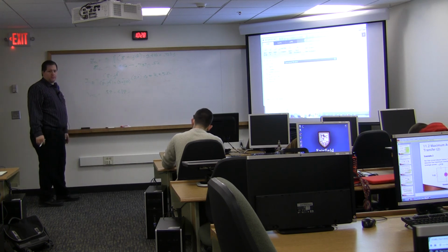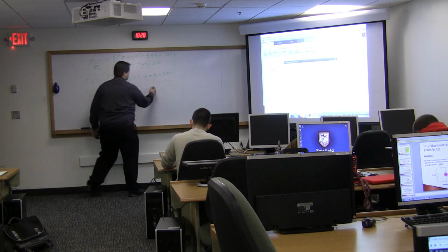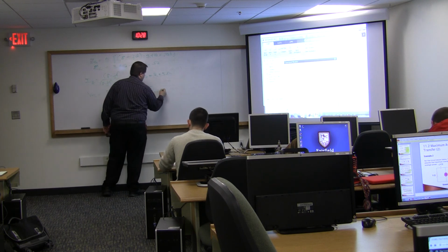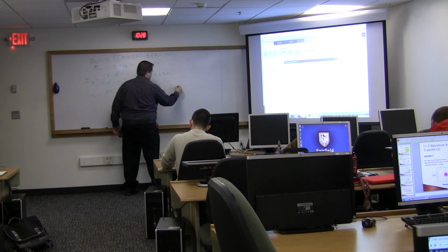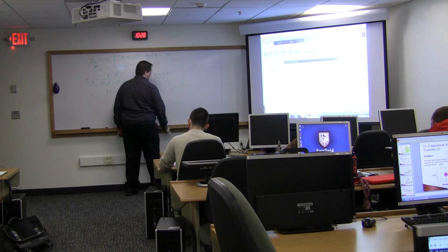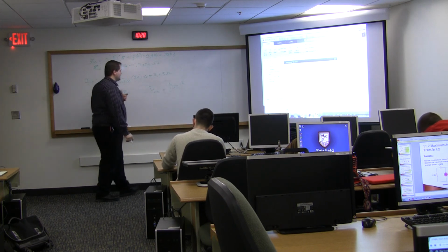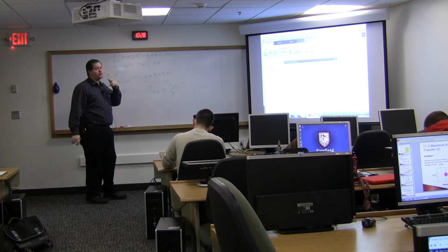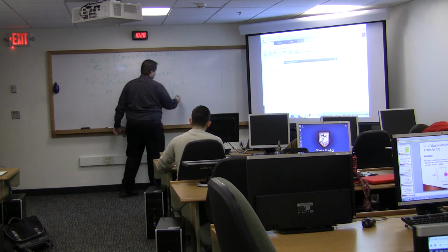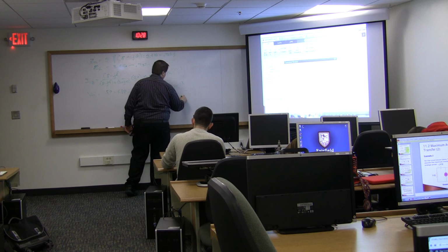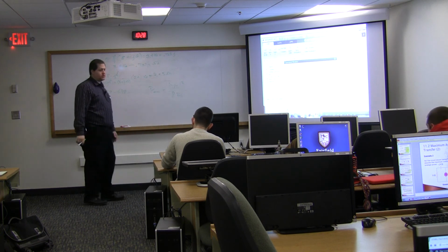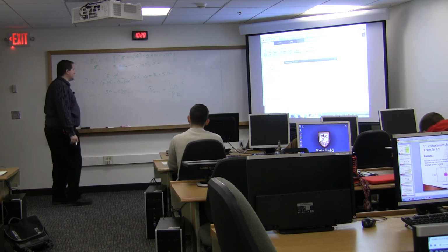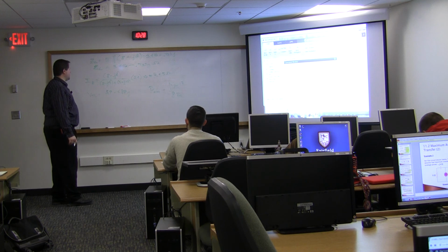Maximum power transfer. VTH magnitude squared divided by 8 RTH. Oh, this is the maximum average power transfer, right? So RTH is the resistance part of my equivalent impedance.